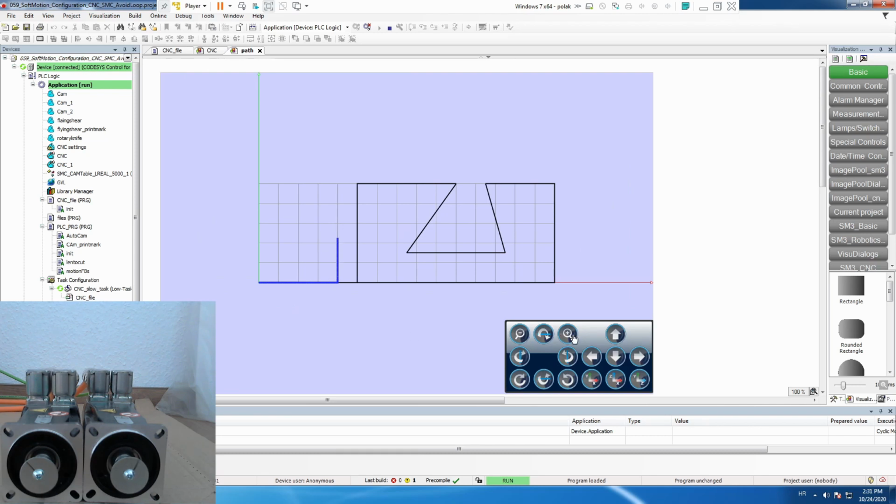So here you see, in comparison to the previous video, the radius of our tool is much bigger. And then we wait here. The problem here is that to avoid this and this, the path will do a loop. And why you want to avoid the loop is going to be nicely visible in a couple of seconds. Because if your tool is wide, you will destroy this part or this part. So this is mainly for your grinder or cutter application. And now you see clearly what the problem is.